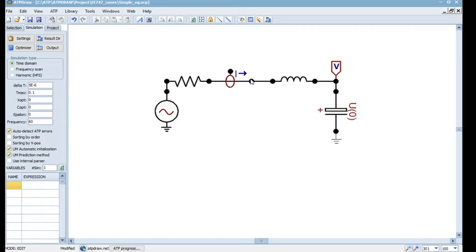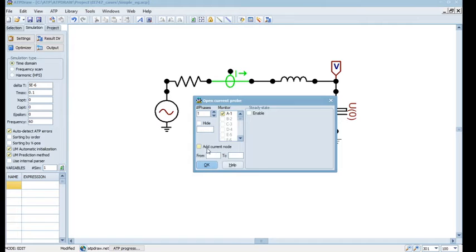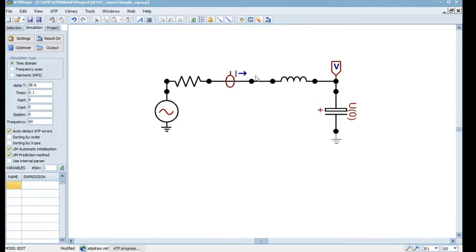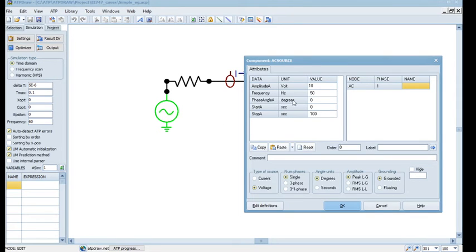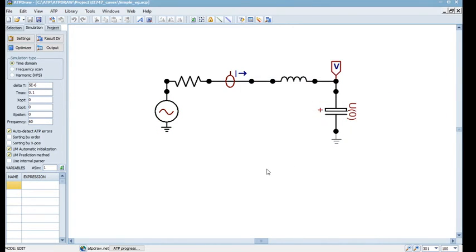Yeah, so having done this, and again you have 3 nodes here, but let me just show you. When you double click, you have an option called current node. So you can use this current for some calculation or some other circuit later, but we don't want it. We want to make it simple. So let's say okay, yeah, that's it. It just gives you current in this direction and this voltage VC, in fact. Yeah, and the switch is imbibed within this. The source here, it's 0. Just keep this in mind. Fine. If you start with -1, you will not see any transient, so to speak. But if you start with 0, the source is started at 0. Fine.